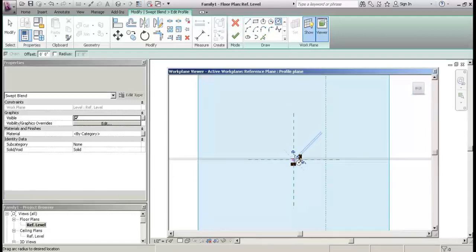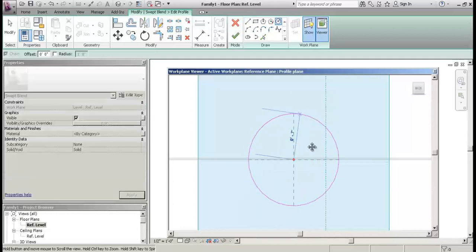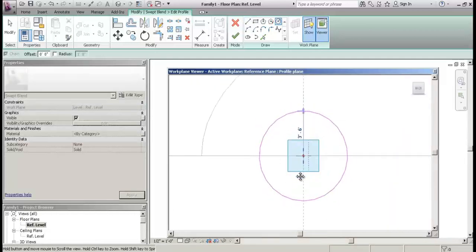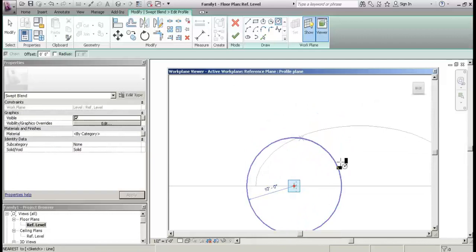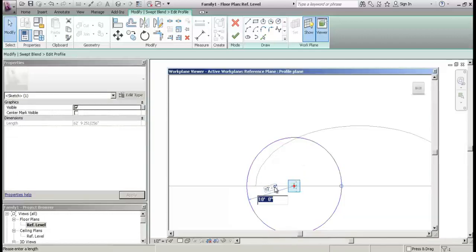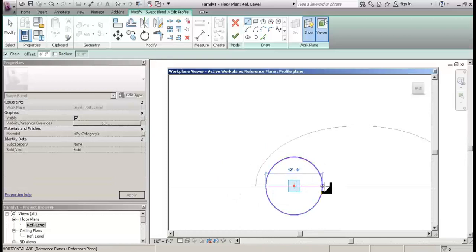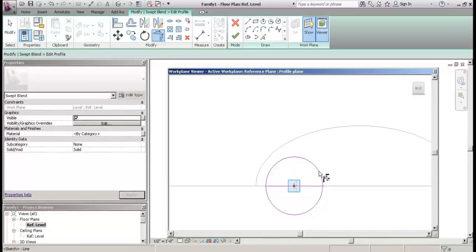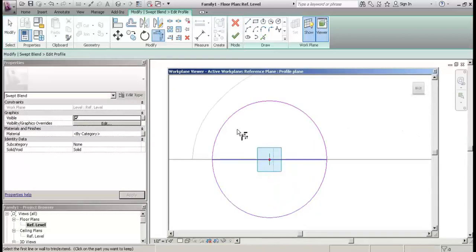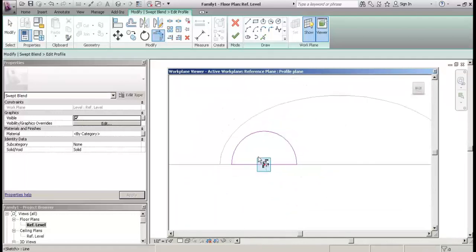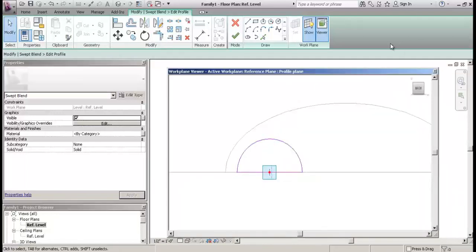So in this case, I will select the circle and drag that up and make the circle now somewhat to the size of what the other one was, and it's at 10 feet. Let's say I want the circle actually to taper down to 6 feet for a radius. I'll draw in my line, drag that over, type TR for trim, select the piece I want to keep, and then select the top left and bottom piece. Now I have a hemispherical cut on that circle.